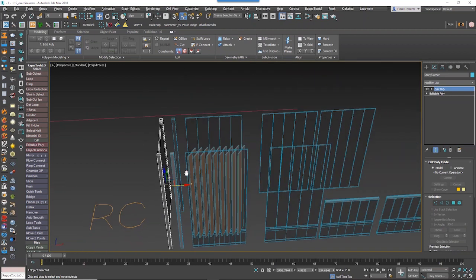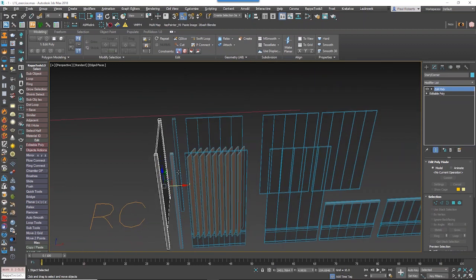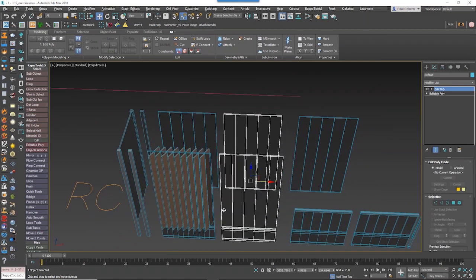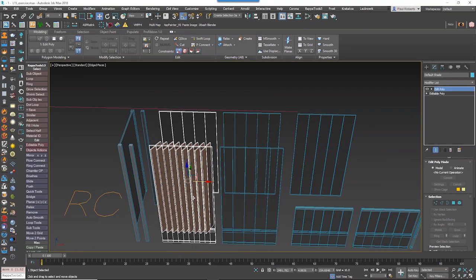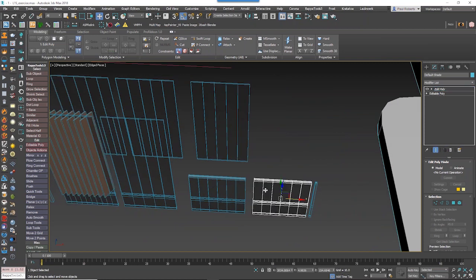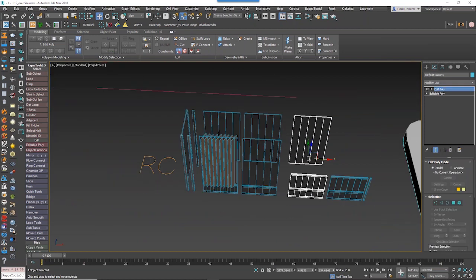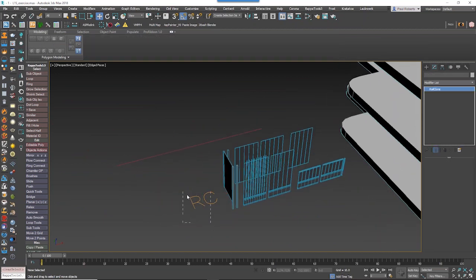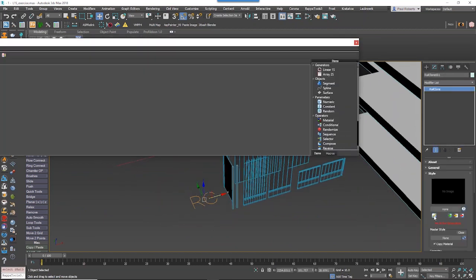I've also got some slices of facade here that I'm going to use. So this one will be the start and the end. This one here is going to be the evenly. I've got just a default piece here, just glass basically. I've got a glass piece with a shade behind it. And then I've got some balcony pieces too. And we build it up like this. So here's my RailClone object in the scene already.